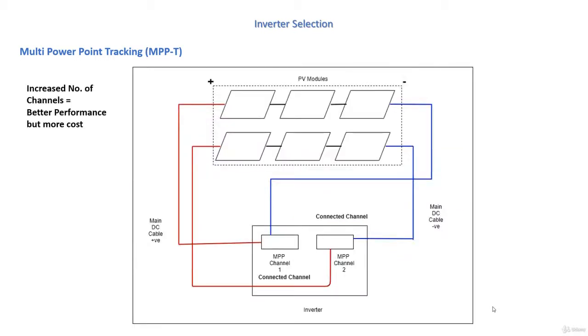A free MPP inverter is an inverter that contains an MPP channel that's connected to a PV system and another one, or at least one, free channel. You can connect or use it, and you choose to use it or not. Both ways the inverter will work. Some inverters must have fully connected MPP channels to operate or work.